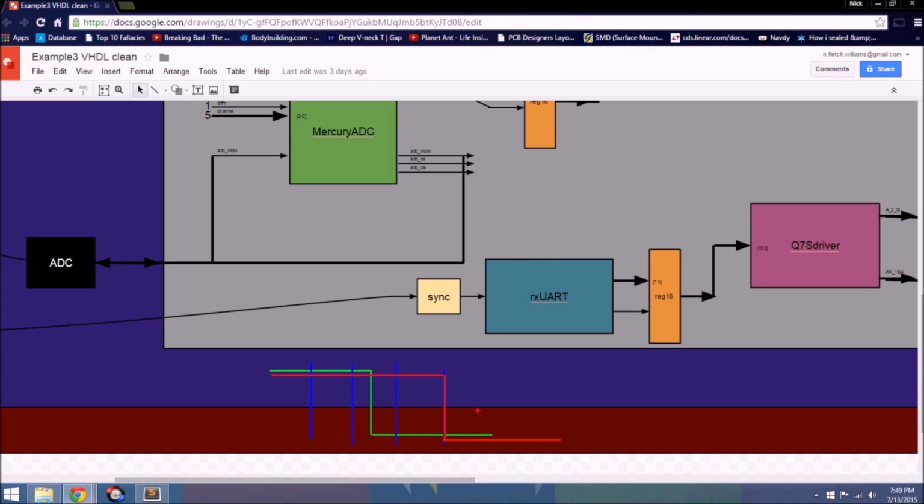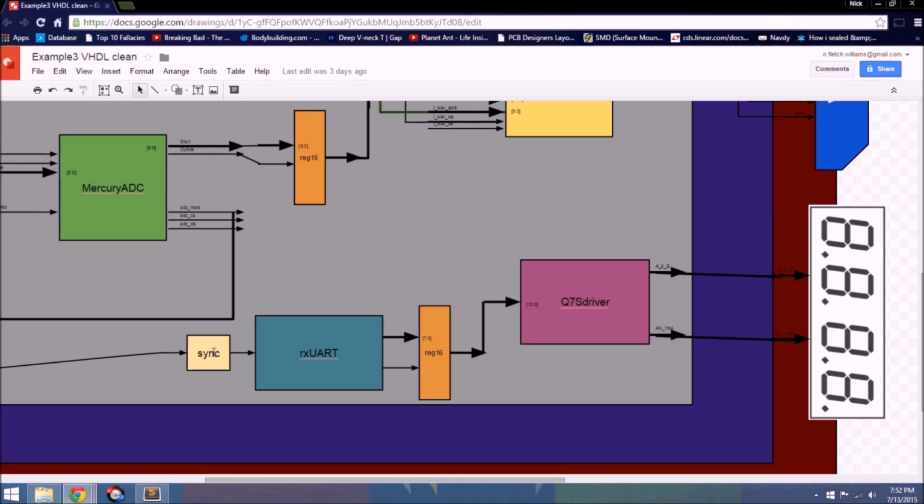So this probably seems kind of useless at first, and I wouldn't blame you if you thought this was pointless. Counterintuitively, this is actually extremely important. I personally have been pretty badly burned by not using these sync hardwares, and I would have really strange symptoms that exhibited seemingly impossible behavior. So it's best to save yourself a headache and add the simple sync piece to your design. So like I said, the sync hardware just matches the rising and falling edges of your input asynchronous protocol to a rising clock edge.